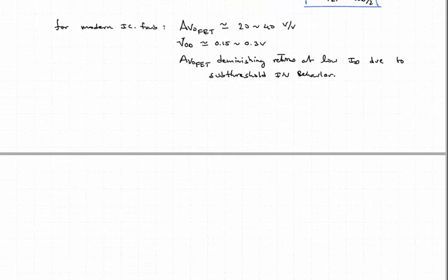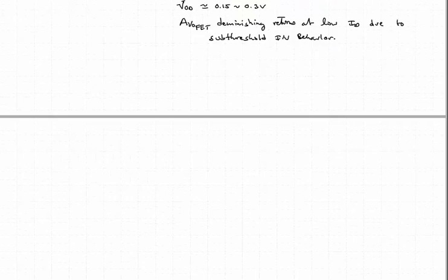Now let's look at a bipolar gain block. So for the bipolar gain block, we have a similar situation where we also have RO, and here we're going to go straight to looking at how we can maximize the gain. So we're not going to have any collector resistance. We're just going to have this current source. I'll go ahead and draw RO as external to the transistor, though you understand it's part of the transistor. And we have VO at the collector there.